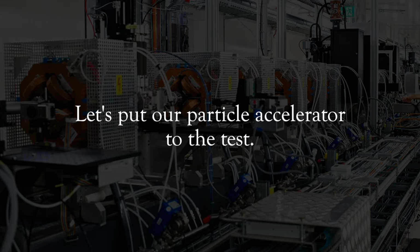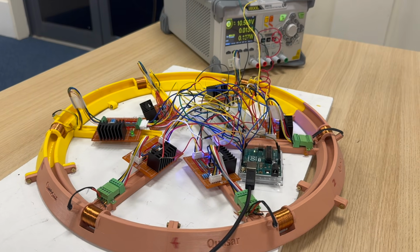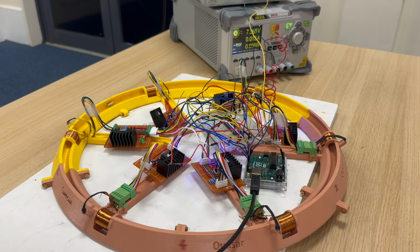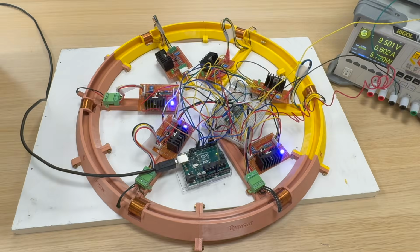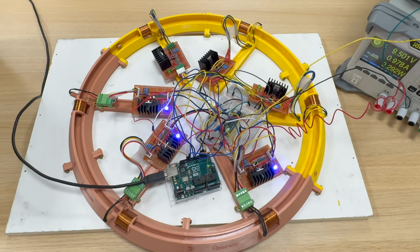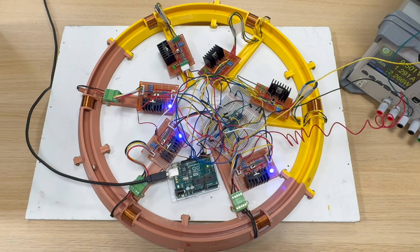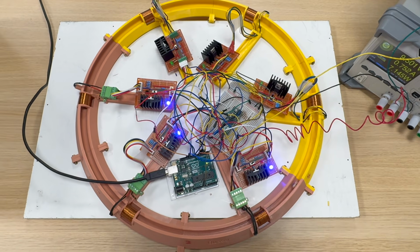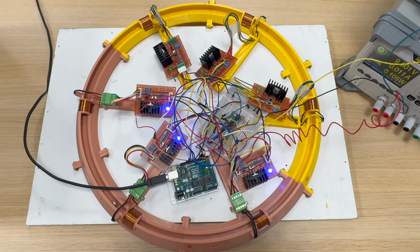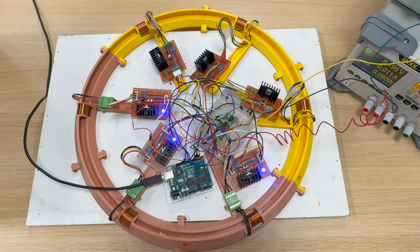Let's put our particle accelerator to the test. Our tabletop model contains 6 sensor coil pairs connected to the Arduino board. Each sensor detects the ball as it approaches, and the Arduino triggers the corresponding coil with a carefully timed pulse. By knowing the distance between the sensor and the coil and estimating the ball's speed, we can choose the delay so that the magnetic field acts mainly in the forward direction. In an ideal case, each coil would give the ball a small push, and the ball would gain speed as it moves around the track.